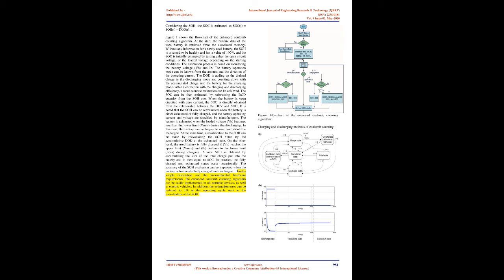Enhanced Coulomb counting algorithm. In order to overcome the shortcomings of the Coulomb counting method and to improve its estimation accuracy, an enhanced Coulomb counting algorithm has been proposed for estimating the SOC and SOH parameters of Li-ion batteries. The initial SOC is obtained from the loaded voltages, charging and discharging, or the open circuit voltages. The losses are compensated by considering the charging and discharging efficiencies. With dynamic recalibration on the maximum releasable capacity of an operating battery, the SOH of the battery is evaluated at the same time. This in turn leads to a more precise SOC estimation.